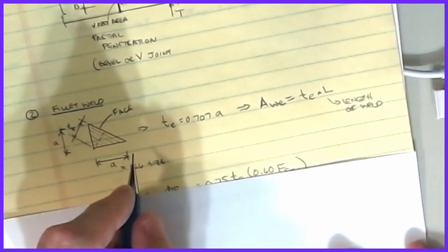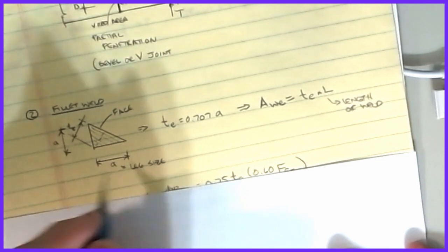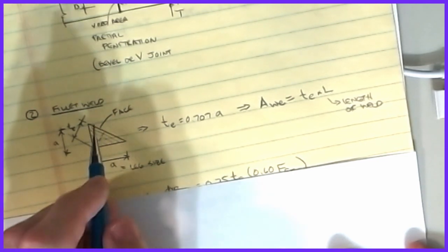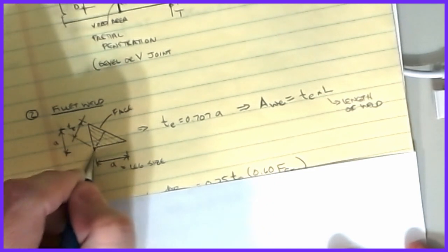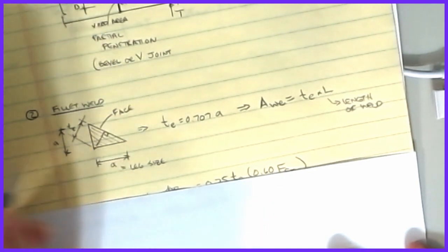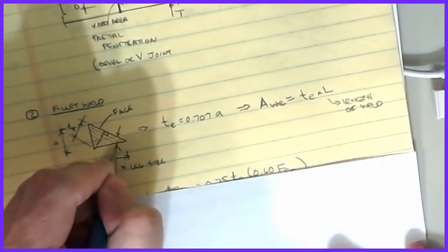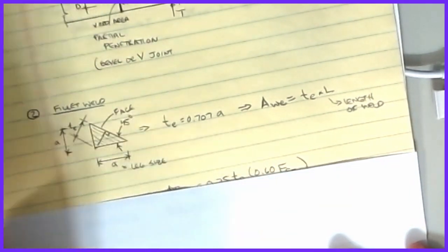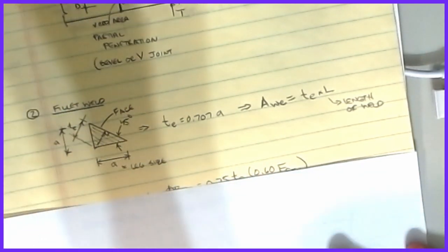And so if you see a 1/4 inch weld, that's what they're talking about, the leg size is 1/4 inch. However, for strength, when you're checking the weld, the shortest distance that will shear or fail is this line that comes right across here and goes 90 degrees to that line. Typically we assume that these are 45 degrees, right? And so the shortest distance here, that's TE.